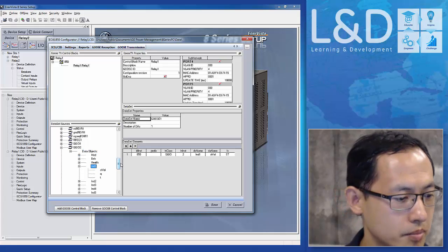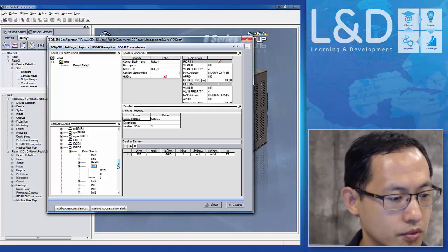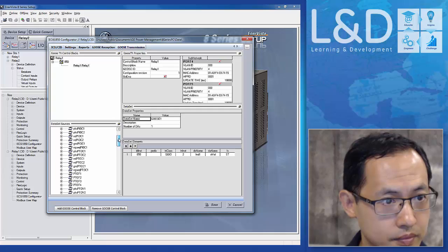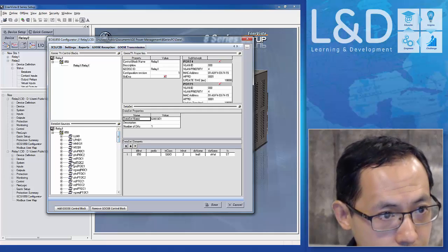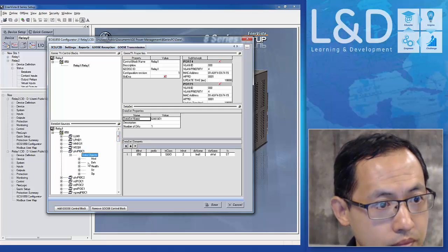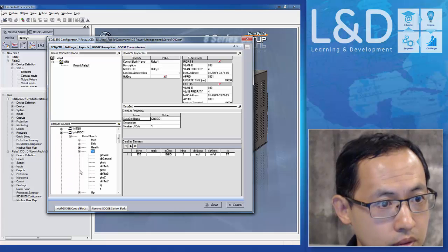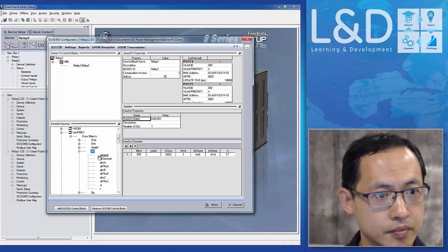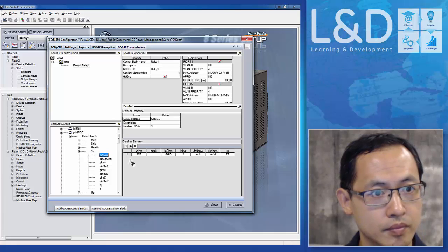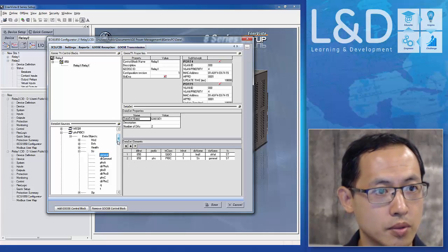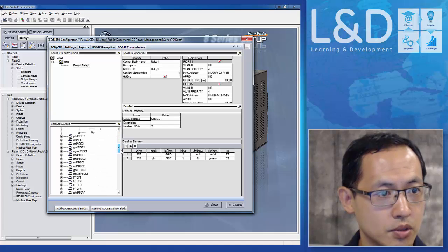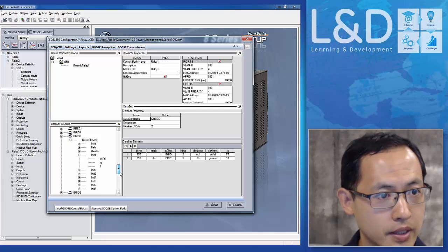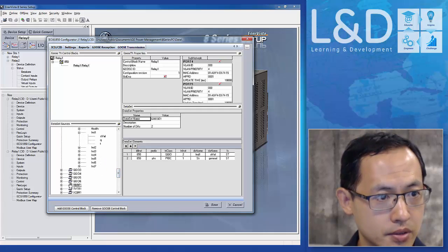Then I'm going to publish the GOOSE message for the phase IOC pickup, STR, that's for the pickup. Then I also want to publish the GOOSE message for the operation relays, so that's GGIO6.